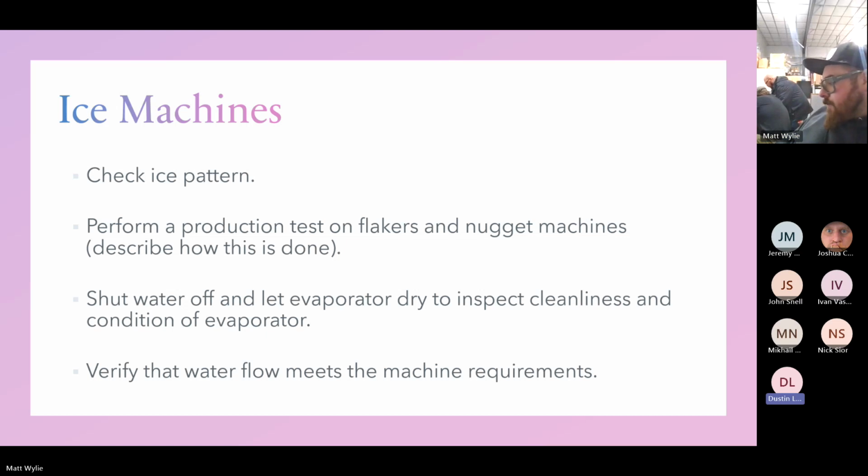In Ken's picture, there's a little silver pin. If you ever change an expansion valve, it's going to come with that. Please put it on the cap tube because it tells the next guy what cartridge size. Obviously, your cartridge size is more about the flow, but at least you have an idea. If it's a VC, it's probably an R22 medium temp valve. If it's a VZ, it's probably an R22 low temp valve. And if it's an SC or SZ, it's probably 404 or 404 related refrigerant.